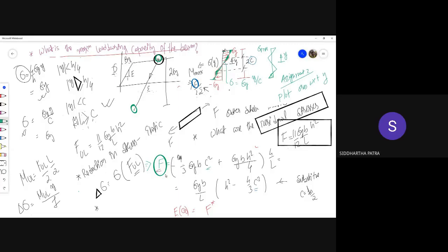No, the point is that this is the stress distribution, the red curve that you have got through elastoplastic deformation. But if there were only elastic deformation, we would have got that green curve, and because the unloading is completely elastic, the green curve represents the reduction in stress in the unloading process. So the green curve must be subtracted from the red curve to have the residual stresses. And your assignment number 2 is to plot the residual stresses with respect to y. Is it clear now?